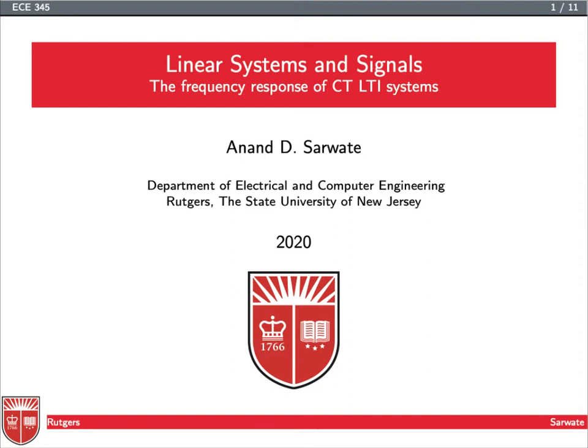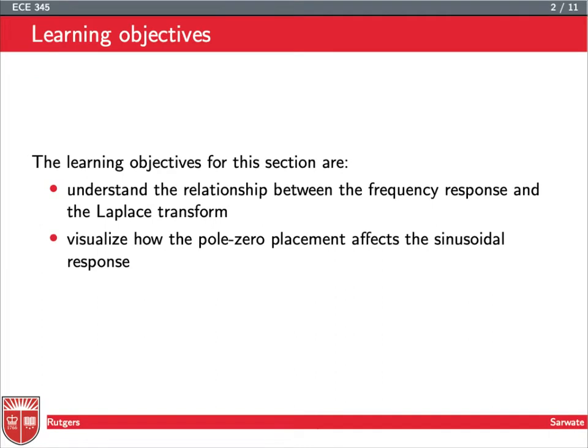Now I'd like to dig a little bit more into the frequency response, which we'll see more of when we talk about Fourier transforms. But in particular, I want to visualize how the frequency response relates to the Laplace transform of the system. So we'd like to understand this relationship between the frequency response and the Laplace transform, and then visualize the effect that poles and zeros have on the frequency response.